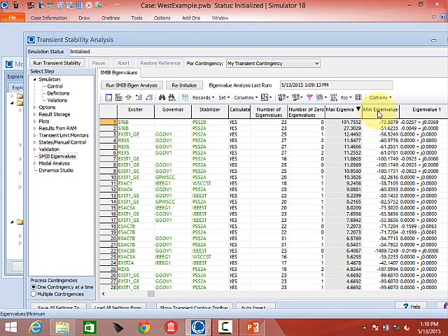But also, you can have positive eigenvalues in a model, and if that mode never gets excited, it's okay. That's why I say don't go looking for trouble. So don't say, wow, I've got all these positive eigenvalues, this case must be horrible. That's not necessarily the situation. It's more if you've got a problem with a generator, where you see in a run that this generator is behaving strangely. Why might that be? That's where this becomes most helpful.